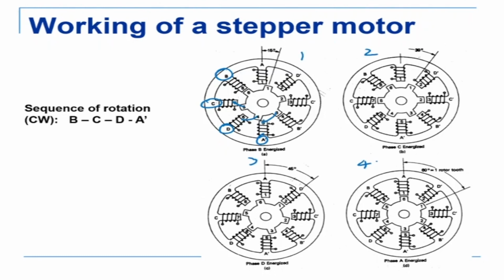What has happened here is pole number 3 has got aligned with this 5th coil. So it has rotated clockwise by a number of steps. Now the steps can be of 1.8 degrees normally, and you can have micro steps, micro stepping.